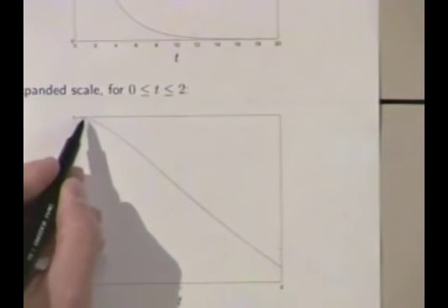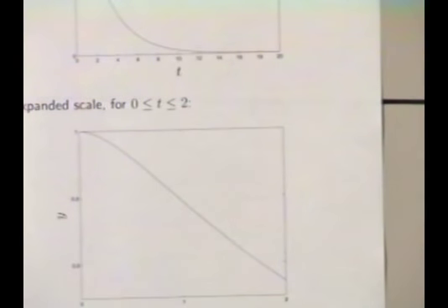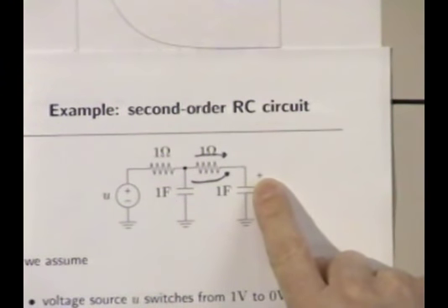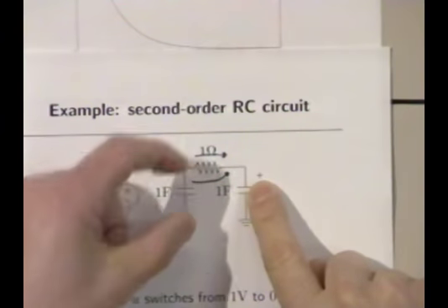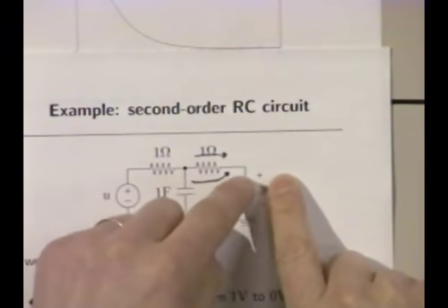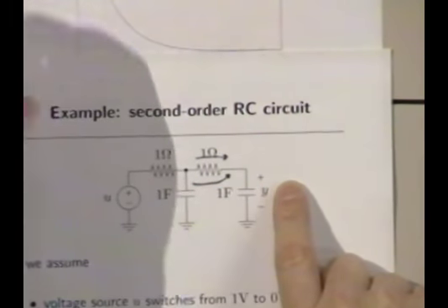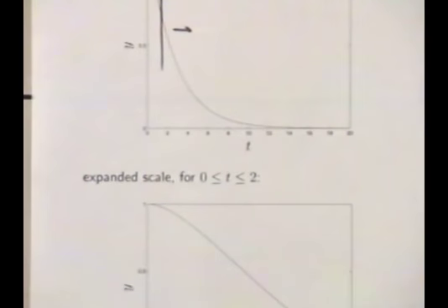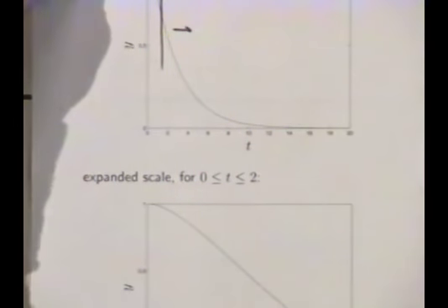And in fact, the fact that this is flat makes perfect sense. What that says is that the voltage on the second capacitor can't do anything until the first capacitor charges up, because it gets charged off the first one. Everybody understand that? In other words, this capacitor gets charged by the voltage here. It has to wait until you build up some voltage here before you can get some serious charging action over here. What that means is that for small times, the voltage stays 1 for a while. I guess discharge is the right way to say it. But okay, so that's an example.